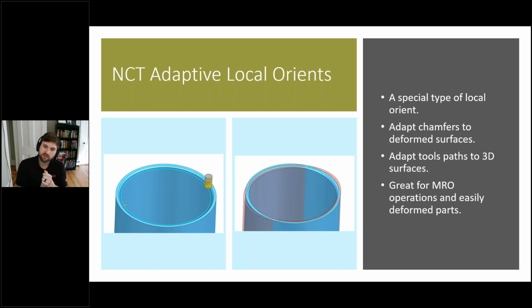And in the example I have here, it actually comes from a real customer. We have a customer that was cutting these very large rings. And these rings weren't perfectly circular. They were kind of egg-shaped in reality, but the CAD CAM guy saw a circular ring on his screen when he was programming it. So real life did not match what he was programming to. What we were able to do is come in here and probe all the way around the inside of this ring, see what that ring actually looked like, and then adjust the cutter path to match that ring.